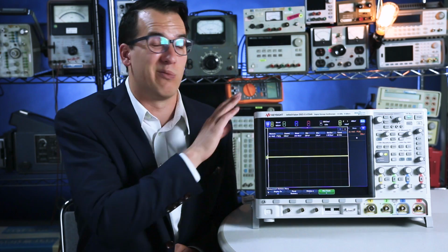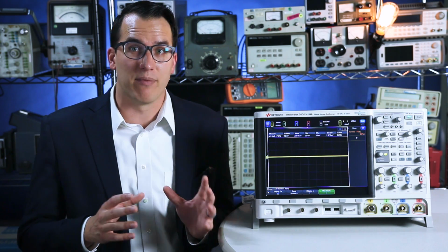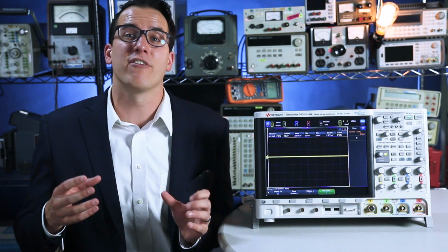It's also worth noting there's a lot of factors that play into noise. So your board, your probes, your scope, whether you warmed it up or not, those are all going to affect your noise measurements. Now, noise is also not always exclusively random. There's always going to be a random component, but the environment that you're working in can also introduce noise into your system.